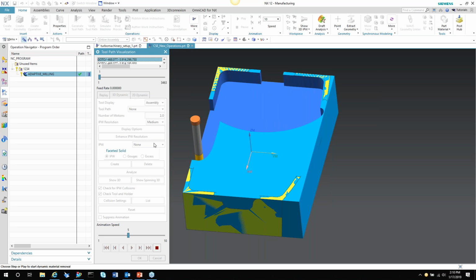You're not going to hear different variance in the tool load. You're not going to get chatter in corners. You're getting the full efficiencies and the full benefits of a trichordal cut pattern, but in an adaptive roughing style pattern. So if you were to compare this to something like iMachining or volume mill, you're going to get around the same type of toolpath. It's the same type of strategy and the same type of effect.